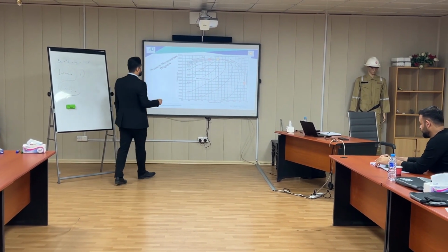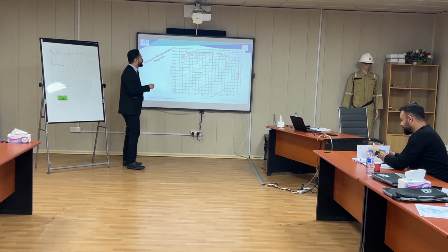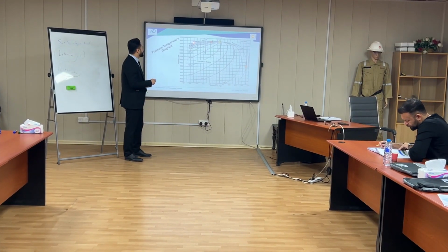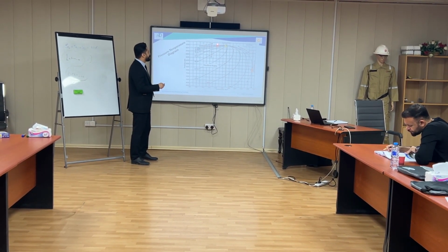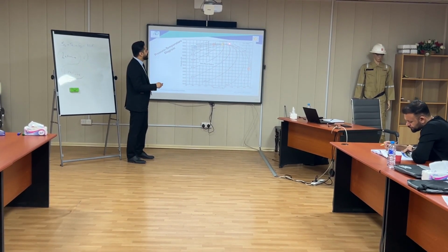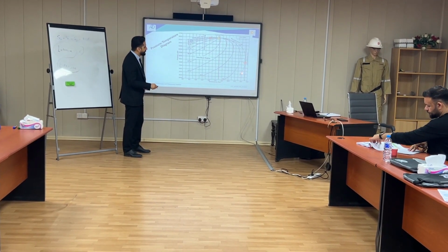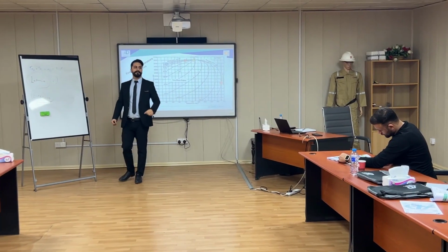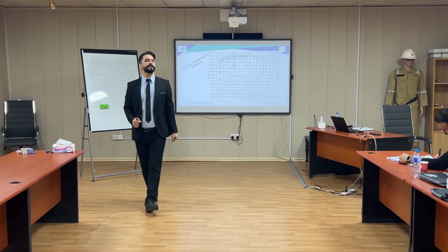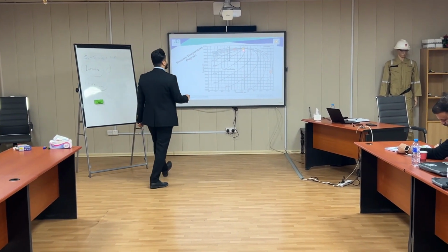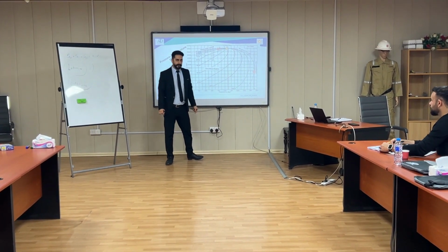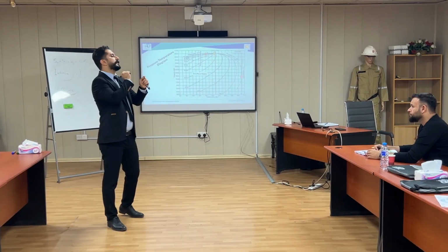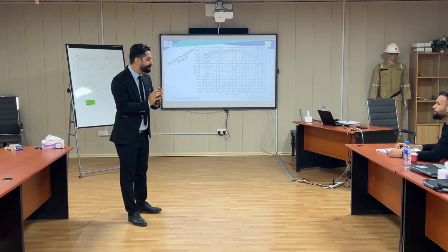Look at here. We said that we are going to find an envelope here, and if you wanna follow it, this point is called B, this point is called D, this point is C, and it will come to E and A point. All of these different points are important for us, and we are going to find out what are the definitions of them. Till now, look at here, this is the critical point, and we talked about it. The critical point is the point at which the intensive specification of the gas and liquid are the same, okay?